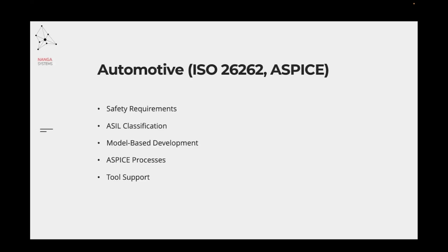Looking into the key use cases that we've talked about, automotive best practices can be the management of safety requirements, identifying and documenting functional safety requirements as per ISO 26262, and to ensure these are derived from or linked to hazard analysis and risk assessment in HARA elements, either directly or through safety goals.